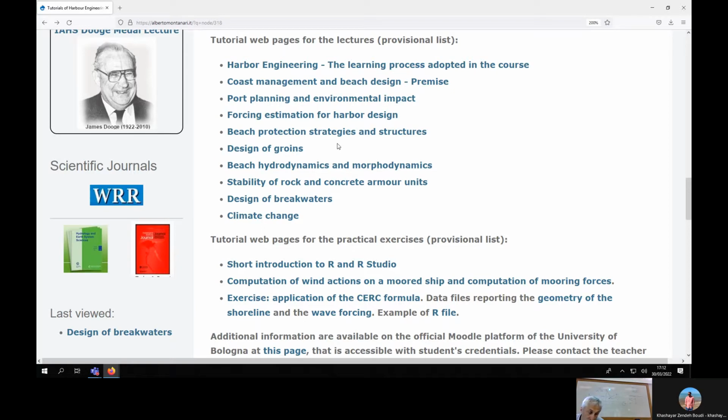And ideally, you don't want to spend much time locating each piece, also because you have to work underwater. So you want to be able to have a very quick and easy allocation of these pieces. On the other hand, you want them to block each other quite effectively, and you want them to be strong enough to remain locked when there is a huge forcing.